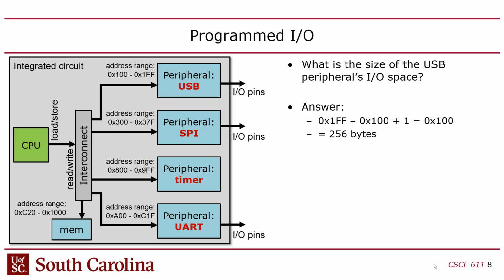So when you're doing on-chip communication to these on-chip peripherals, you're using programmed I/O, which is a parallel interface. You're reading and writing one word, which is a 32-bit value, in one cycle, essentially. But once you go off chip, usually you go serial.